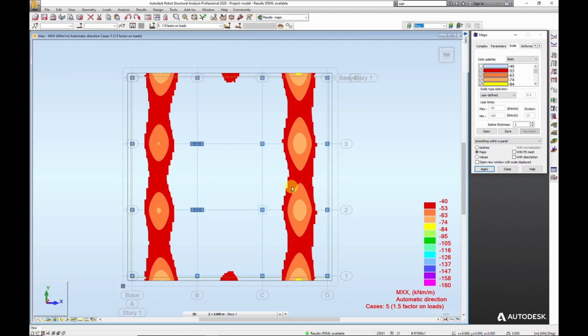You can work out the resistance, and then when you're looking at design, really what you're looking at is how to enhance the reinforcement, maybe by placing additional bars, or maybe by locally increasing the bar size to give you the resistance that you require. So it's telling me here that in the zones that are highlighted by the colour map, that's where I need to enhance the amount of reinforcement.